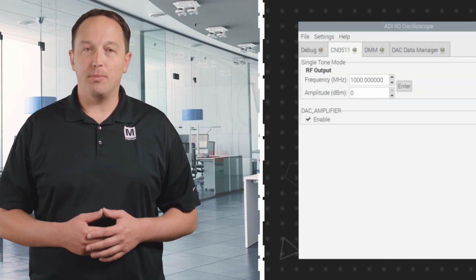With its excellent performance and small size, the CN0511 can be used in a wide range of applications. It can be incorporated into automatic test equipment, used as a portable signal generator. It fully supports 0IF and other DC-coupled applications, and is capable of phase-coherent fast-frequency hopping.